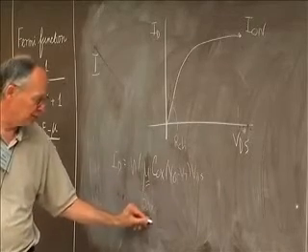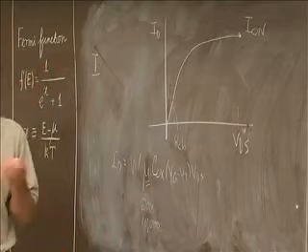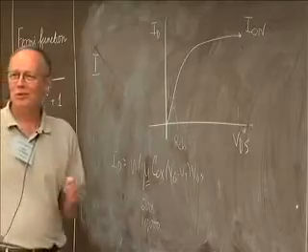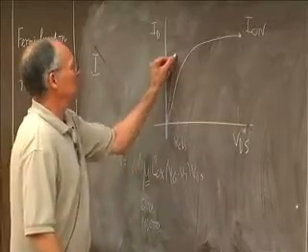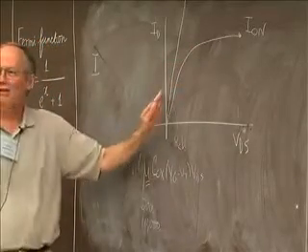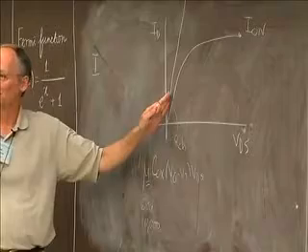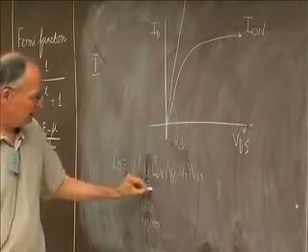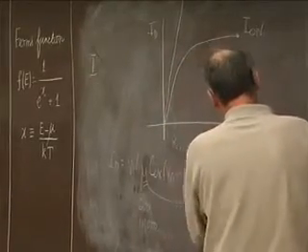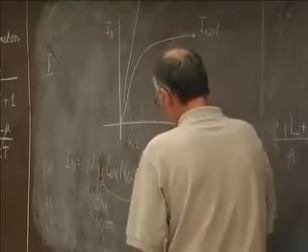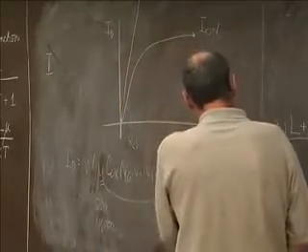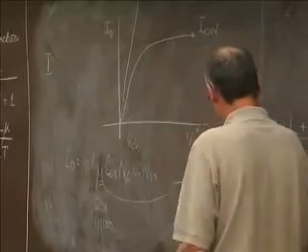Maybe you could get 10,000 on some of these III-Vs. All right, that looks like an enormous boost. But it wouldn't quite work that way. I mean, that would give you more steepness, but you're going to saturate. And also, you can't get steeper than the ballistic limit. So really here, 1 over the mobility is 1 over the actual mobility, which might be enormous for these materials, plus 1 over this ballistic mobility.